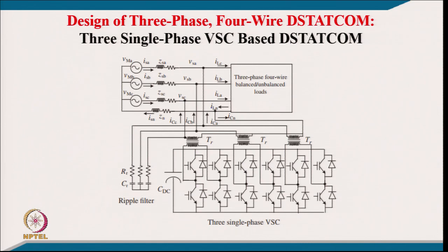And in these three single-phase topologies, one of the major benefits is that you can use unipolar switching. So the ripple current frequency will be double the switching frequency of the devices, or the switch. You can see here the switching losses in the devices will be half, lower in this case, and the DC link voltage can be maintained much lower, approximately half compared to the previous topology.